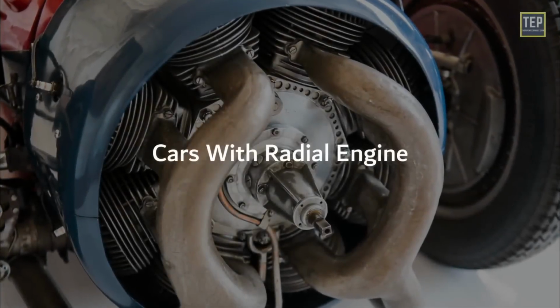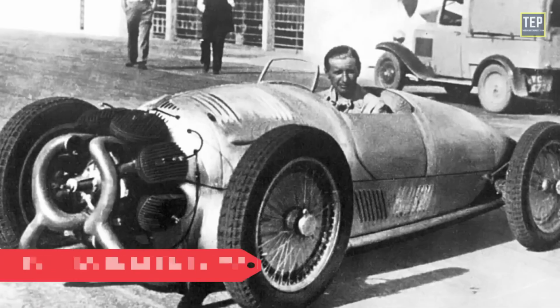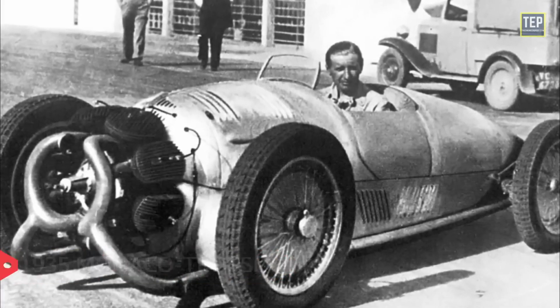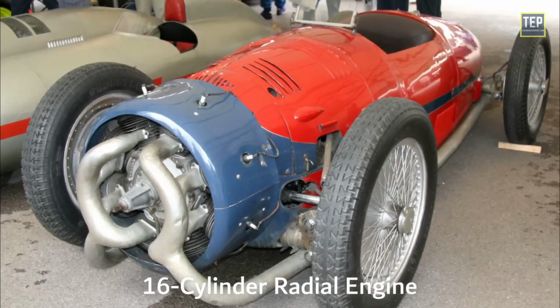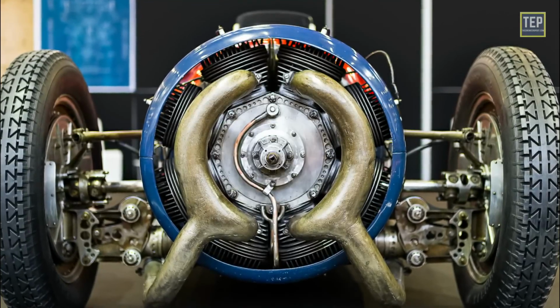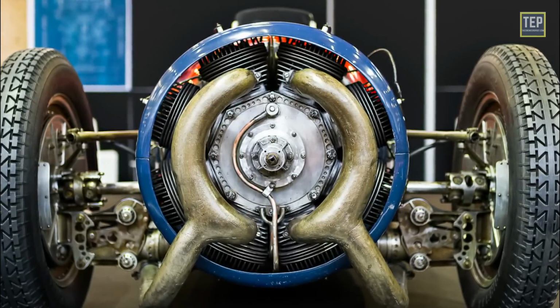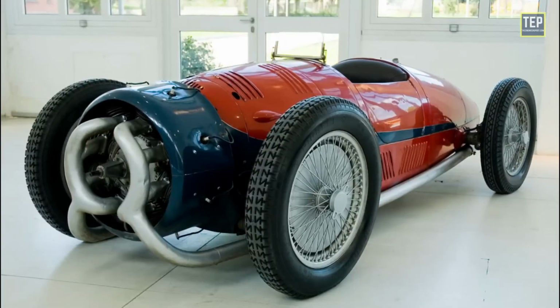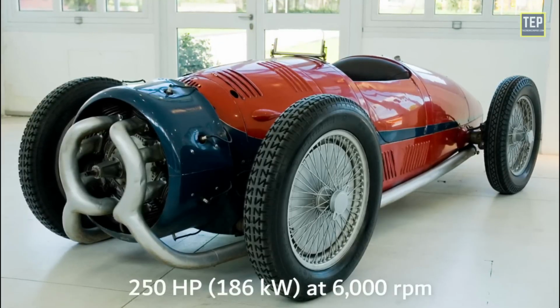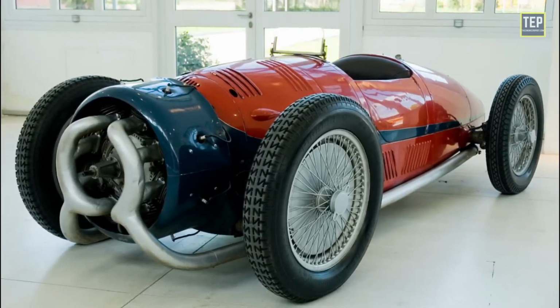Cars with radial engine. The 1935 Monaco Trossi Grand Prix car has a twin supercharged, air-cooled, 2-stroke 16-cylinder radial engine. 2 banks of 8 cylinders were mounted behind each other, with pistons sharing a combustion chamber. This complex engine was light, yet still capable of producing 250 horsepower at 6,000 RPM.